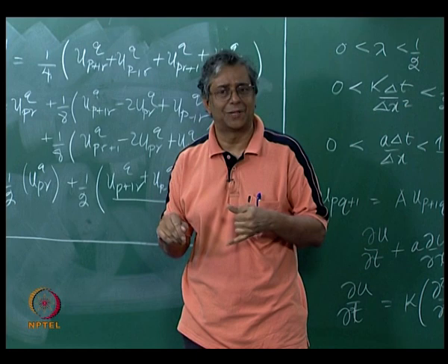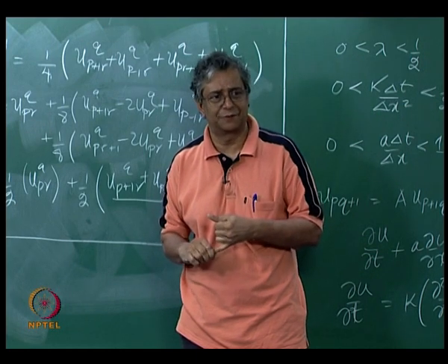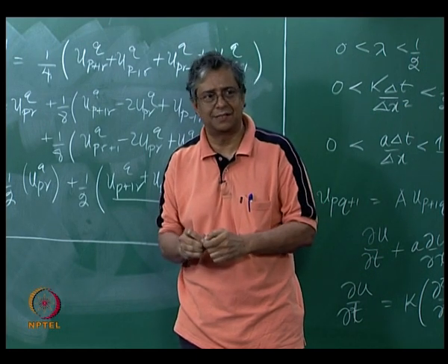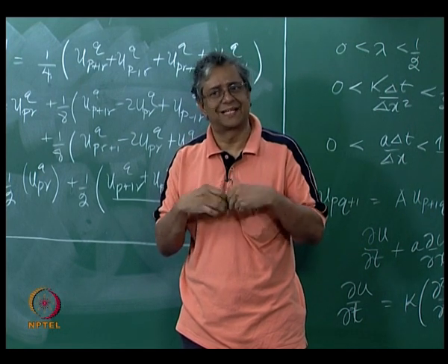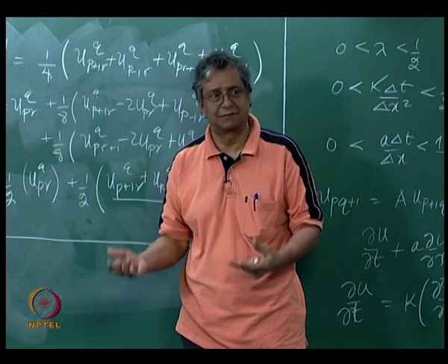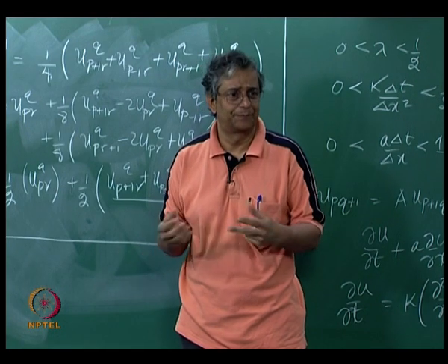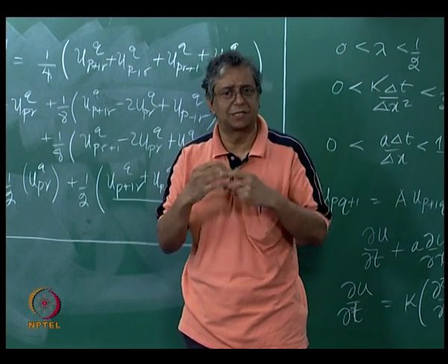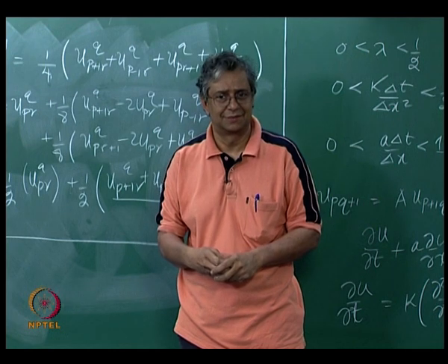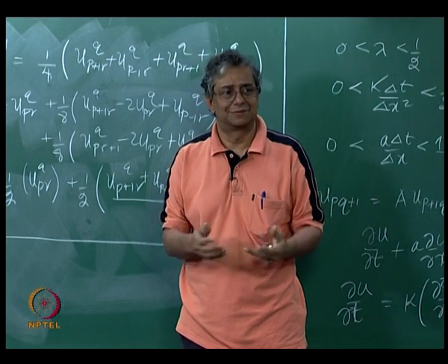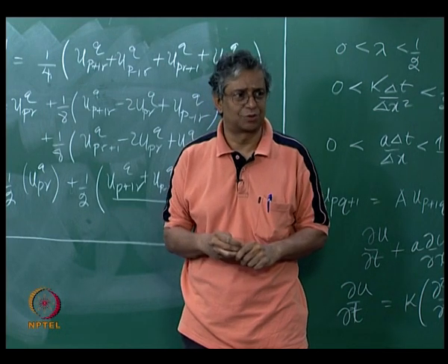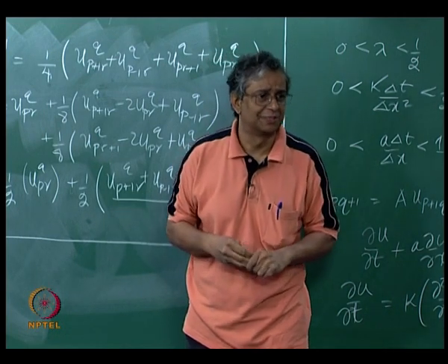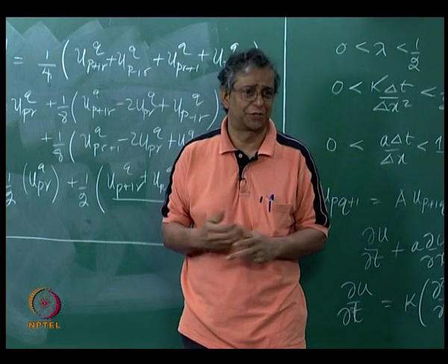The second thing is, if you add a lot of artificial dissipation, the way we are adding it, explicitly at the current time level, actually contaminates the solution. So you could say, hey, wait a minute, I am not actually solving the equation that I set out to solve, anyway I am solving the modified equation, so I am going to add artificial dissipation. That is one argument.